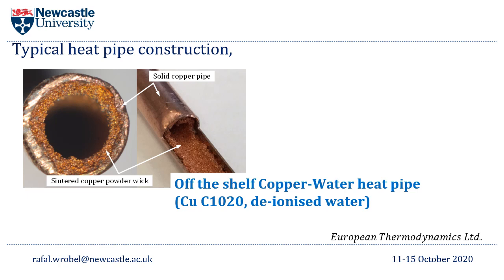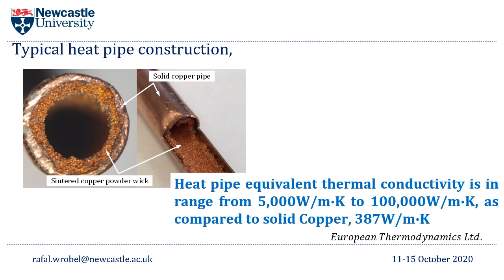as it offers reasonable performance measures when it comes to heat transfer and also operating temperature range. That phase change mechanism allows for achieving significantly higher equivalent thermal conductivities along the heat pipe than could be found for any metallic or ceramic alternative, ranging from 5,000 to 100,000 watts per meter Kelvin. And here, as a comparison, copper is somewhere around 400 watts per meter Kelvin.